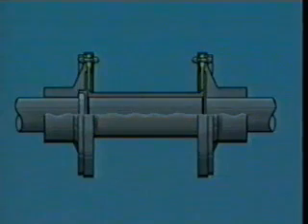All misalignment is handled by the elastic flexing of these thin web diaphragms, and there is no rubbing movement of any parts of the coupling, and no lubrication is required. These couplings can handle fairly large angles of misalignment between shafts. However, this coupling can tolerate only slight changes in back and forth movement of shafts.